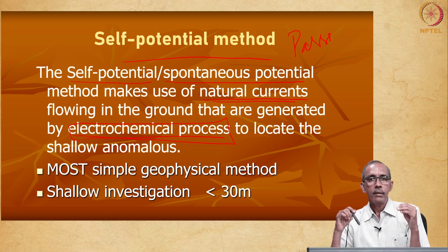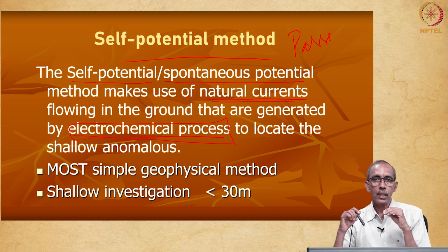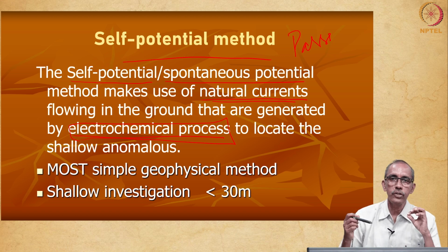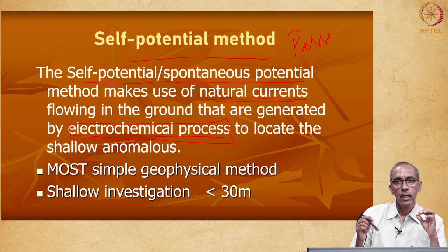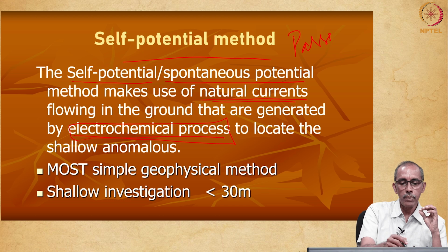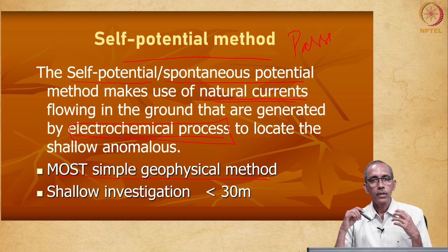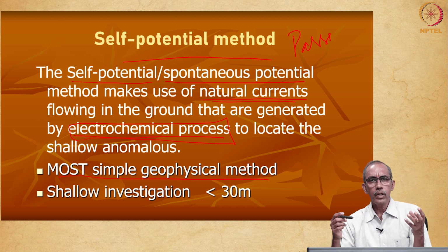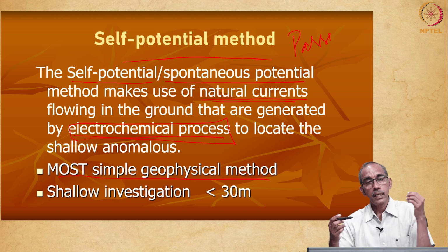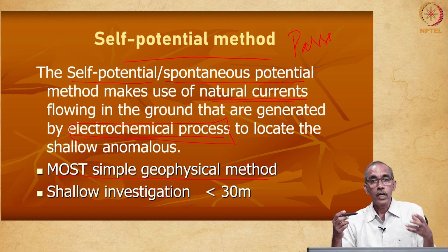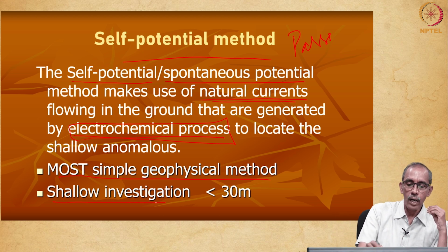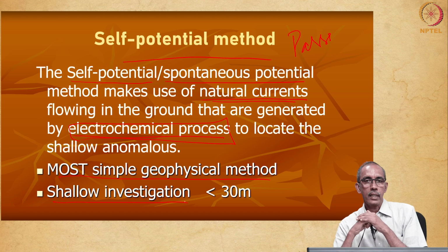Because we are just measuring the naturally present potential, this is the simplest geophysical method which we are going to see during this course. Most simple geophysical method. Why? We are just going to measure the natural potential that can be measured at the surface of the earth, since natural potential which is generated at greater depths will not reach the surface. So, this method is generally for shallow investigation.